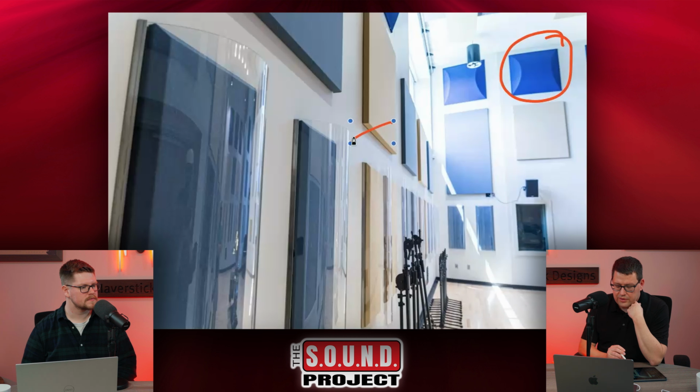With the shield removed, it's just an absorber. It's going to absorb like a 2-inch thick fiberglass panel does. But when the shield is put in place, it creates a barrel shape and gives you absorption coefficients in the 0.99 range at around 80 to 100 hertz. So you get some bass trapping, but then it's more diffusive in the higher frequencies. Sure. That geometric shape is used quite often in a lot of different types of products out there.